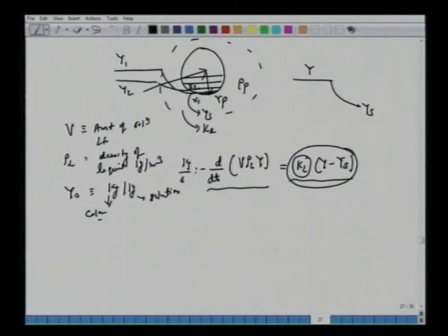This KL times Y minus YS, you must recall, is a flux. So let's say we have chosen these values of KL so that the flux is kg per meter square per second. Recall earlier we used to use moles per meter square per second. So here in case of adsorption, we are working on kg per second. So the flux is kg per meter square per second multiplied by this AS. So what is AS? AS is the external surface, meter square per kg.